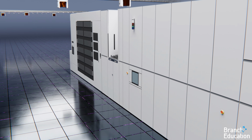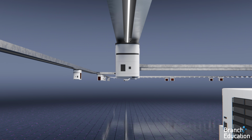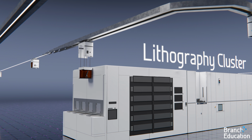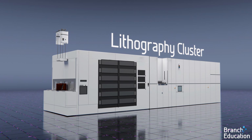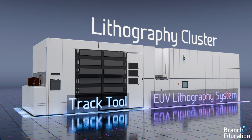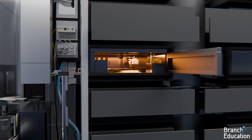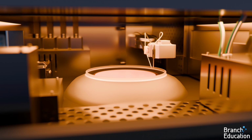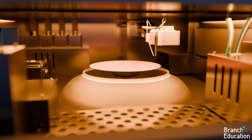Let's start with a wafer that's carried in a FOUP on the overhead transport system. This FOUP lands on the lithography cluster, which is a combination of a wafer track tool and a lithography tool. The wafer first enters the track tool, where a layer of photoresist, or resist for short, is evenly spread across the wafer.